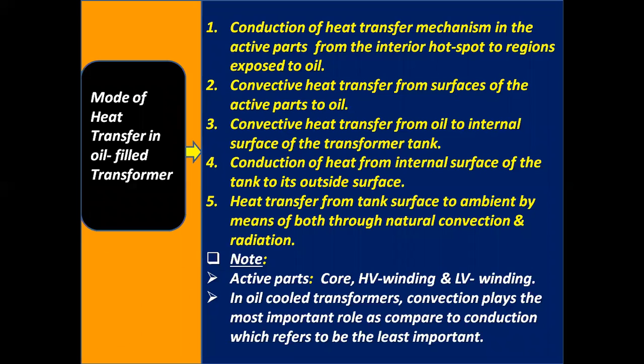Modes of heat transfer in oil filled transformer. One, conduction of heat transfer mechanism in the active parts from the interior hotspot to regions exposed to oil. Number two, convective heat transfer from surfaces of the active parts to oil.